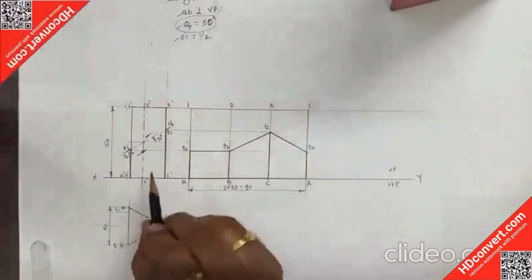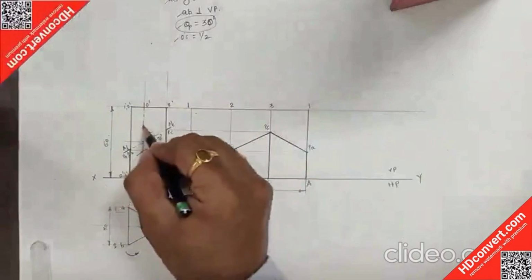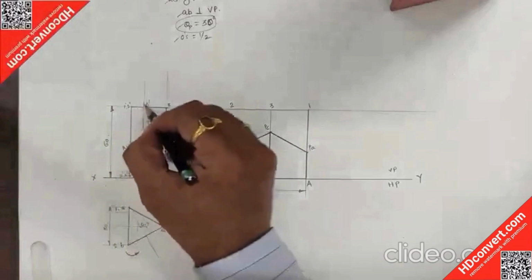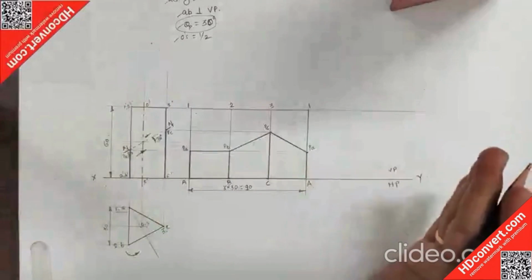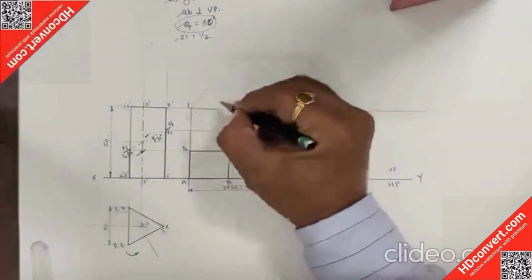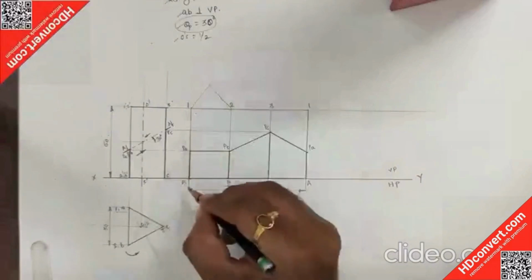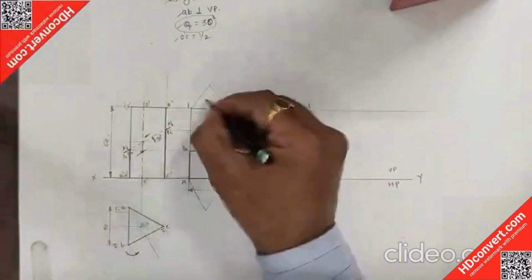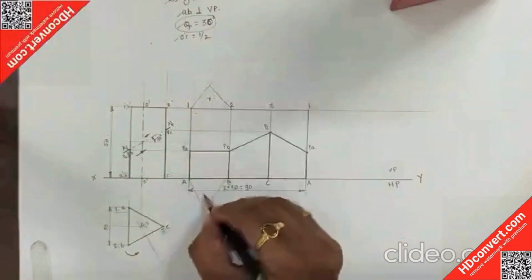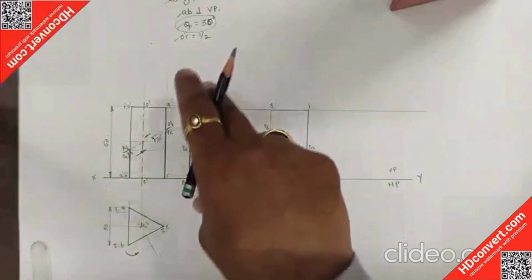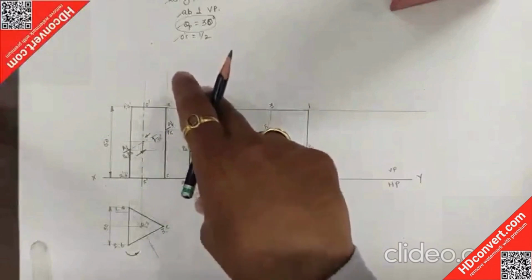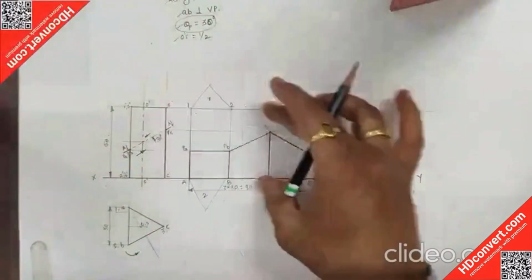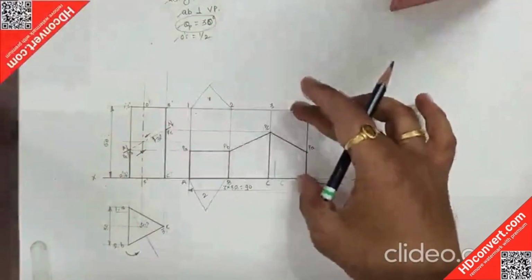Lateral surface means the long surfaces which are parallel to the axis. The base and top plane, which are perpendicular to the axis, we have not considered. Getting it? Because if you draw them here, there would be triangles. These two triangles are perpendicular to the axis, but we are going to develop only the lateral surface, parallel to the axis. That's why the base and top plane we are not considering. This construction is all that is expected in the exam.